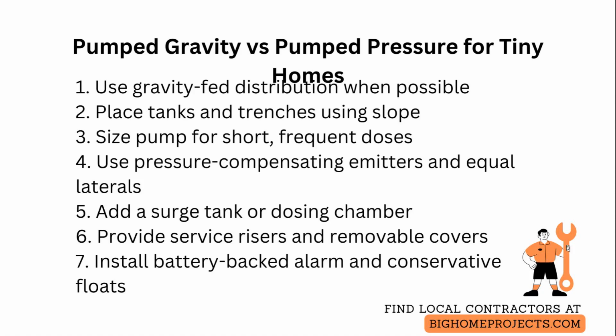Slope allows consistent flow without pumps, so place tanks and trenches to take advantage of natural fall and keep invert elevations accurate to within an inch.